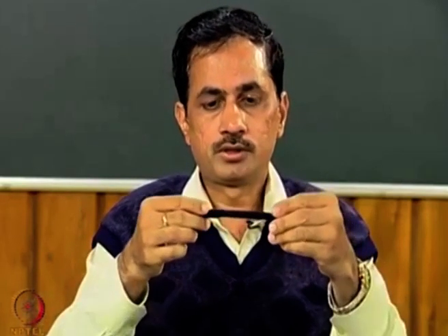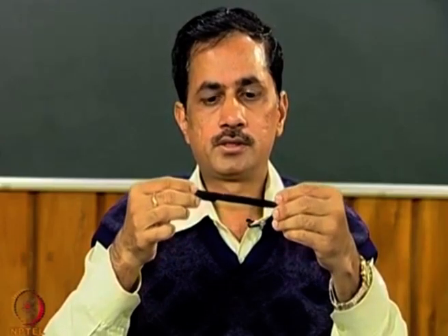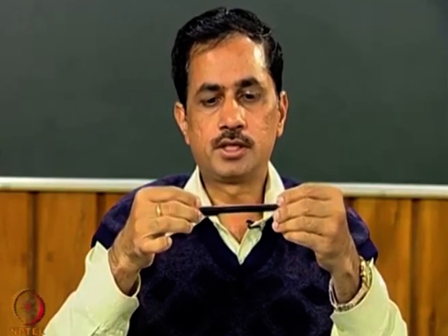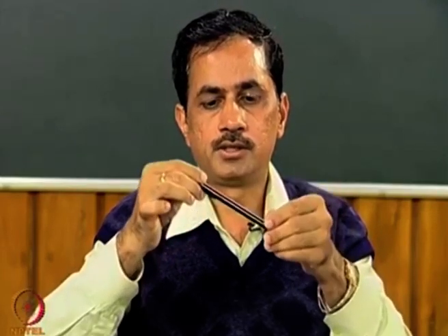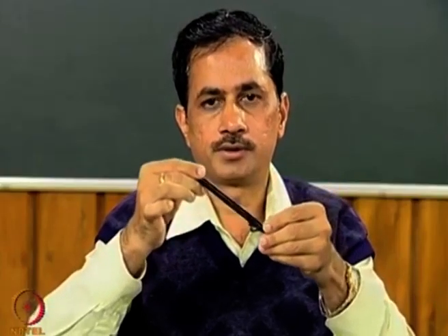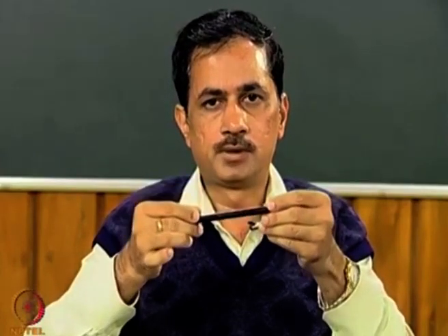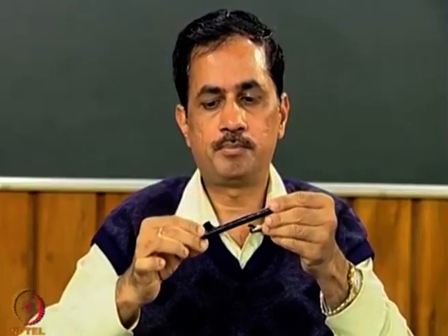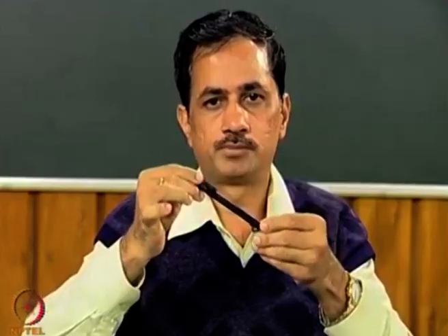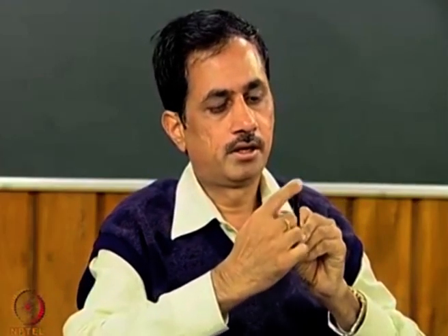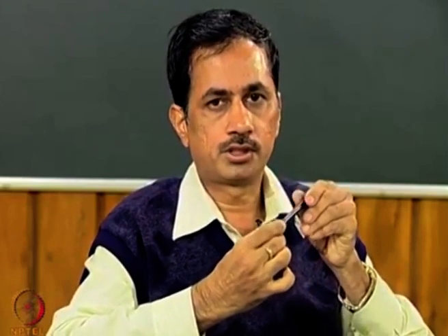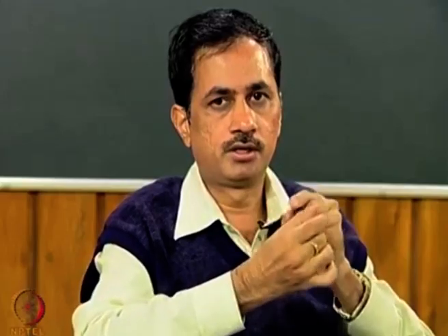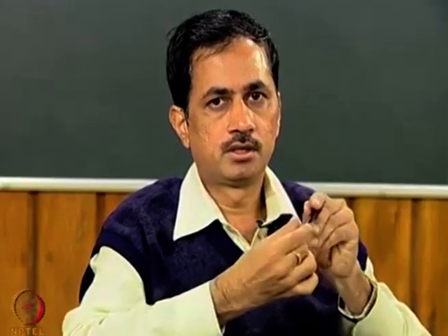The second motion is pure tilting, tilting about its center, so it will be something like this. The center remains stationary and the ends are moving in an ellipse. If we see the path of the end, it moves in an ellipse. If we see from the side, again it has an elliptical path. Not only is it spinning about its own axis, but it also has conical motion about the center of the shaft. So, let us see this particular motion.